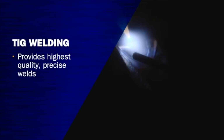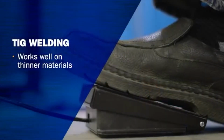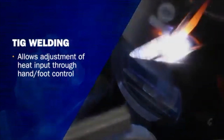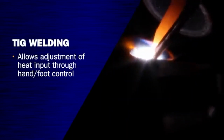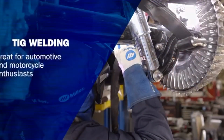Some of the advantages of TIG welding are that you get the highest quality weld, it's aesthetically more pleasing, it's a pretty bead, and it also works great on thinner metals. But the only problem is that it's very difficult to control because you're controlling all 3 of your elements in the process. Your leg is controlling your heat, your opposite hand is typically controlling your filler metal deposition rate, and then of course you have a non-consumable tungsten electrode that is creating your arc as you move through the bead. This is a considerably slower process as well, so usually when you're TIG welding, you're going to be working on stuff like a frame for a motorcycle, automotive, sheet metal, something in that regard.